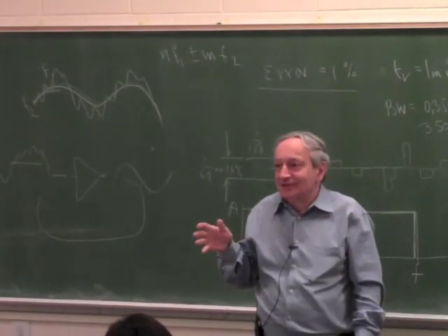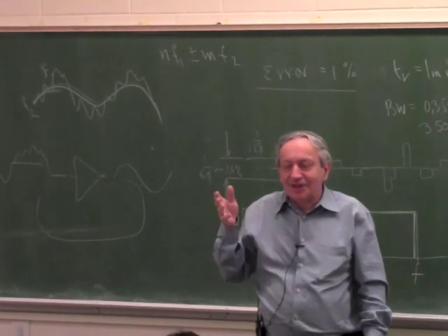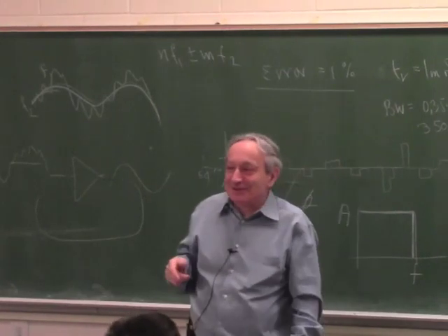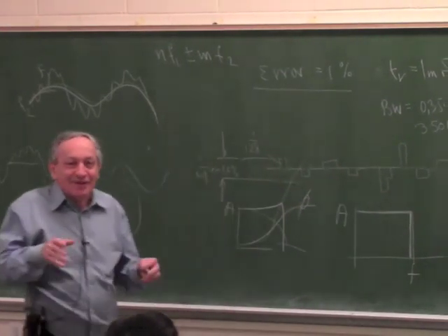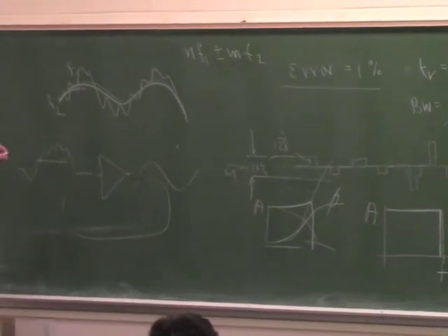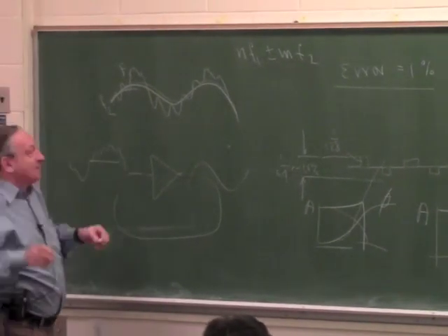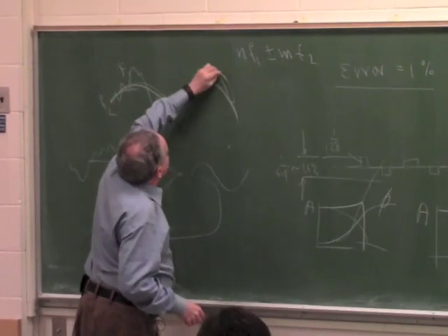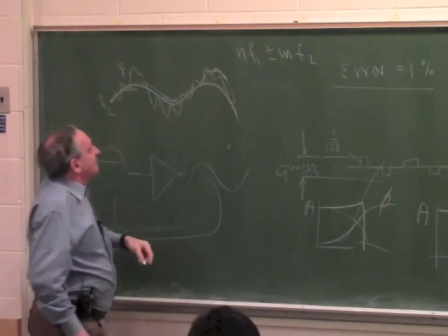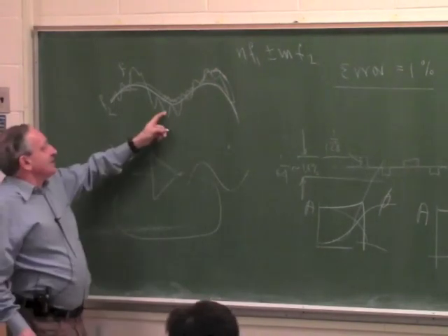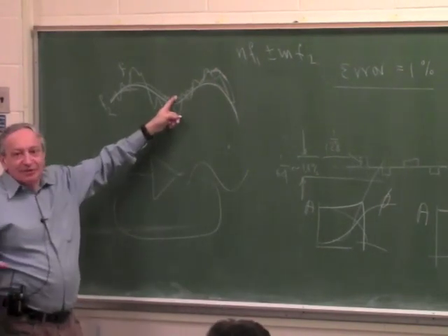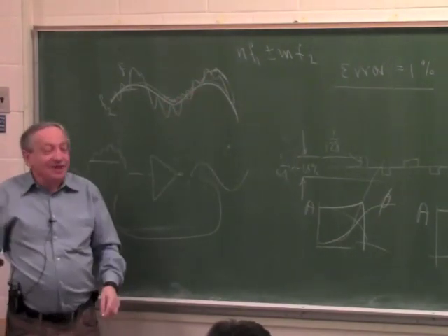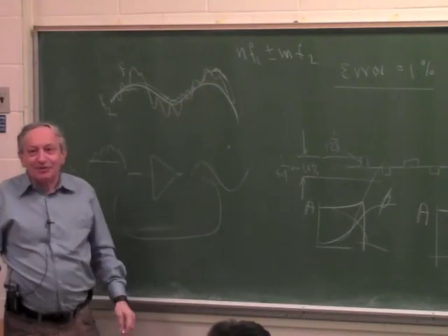And that's from? Where is the 1 gigahertz from? From you guys, smartphones. You are reading this part, right? So if you have a fast enough scope, you will see that on any low-level signal in the lab, there is this, and there is something faster, and there is something super fast, which you need a very good scope to see. And typically there is a 1 megahertz sitting on it, 100 megahertz, which is FM and television, and 1 gigahertz, which is smartphones. And today, probably there's a lot more of the 1 gigahertz than before.